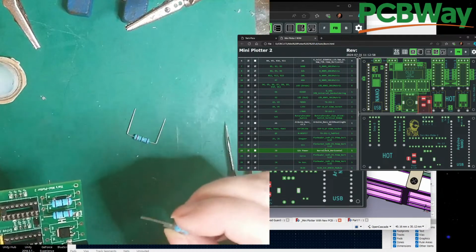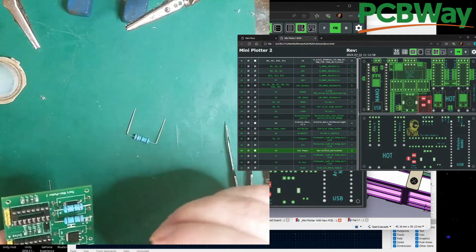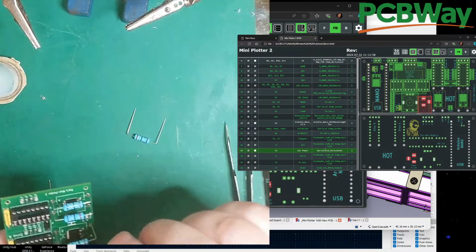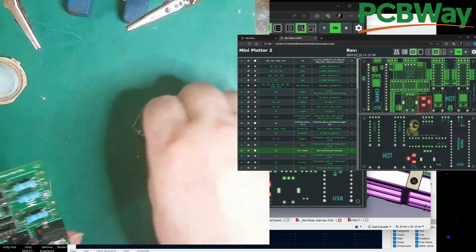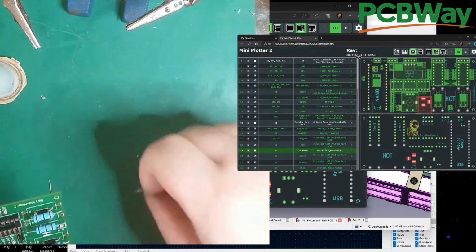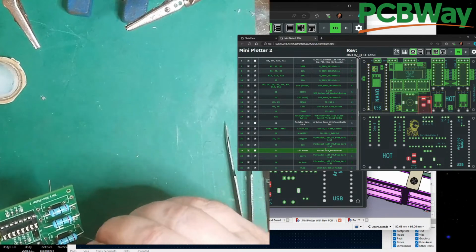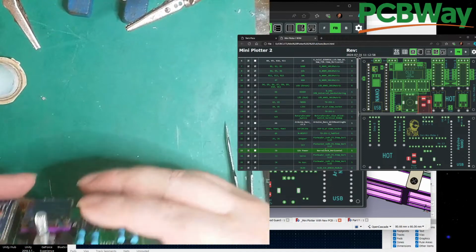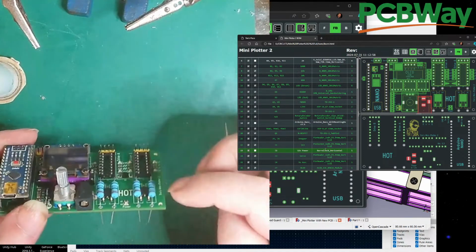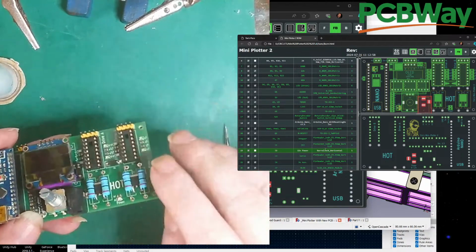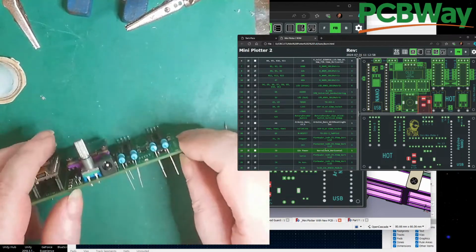All soldiers in a row, all neat and tidy. There we go. All standing to attention. Right. That goes the other way. So they don't want to be right down touching them. These are going to get hot, so you need air to be able to circulate around those.